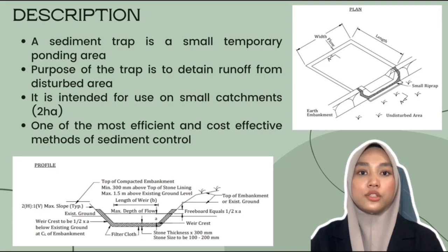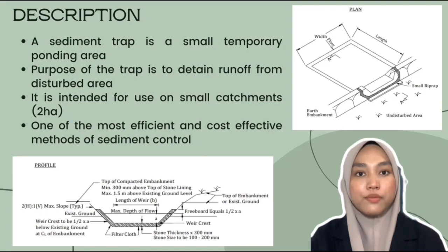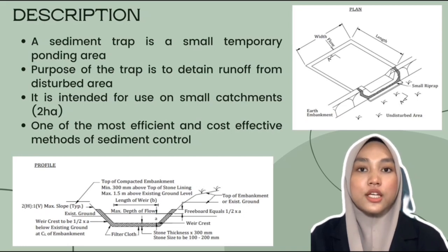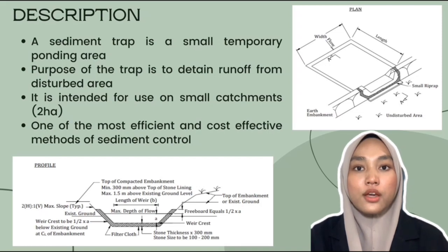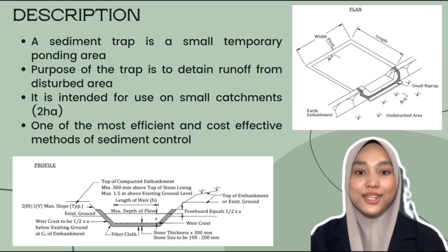It should be noted that since sediment traps are only effective in trapping coarse sediment, a chemical binder or coagulant may be required for fine particle trapping. The sediment trap requires monitoring during each storm event. It should drain within 36 hours after a storm event, following which mechanical dewatering is required. Regular maintenance should include sediment removal after sediment is 300 mm thick, as well as structural and outlet protection inspection. That's all from me. Thank you.